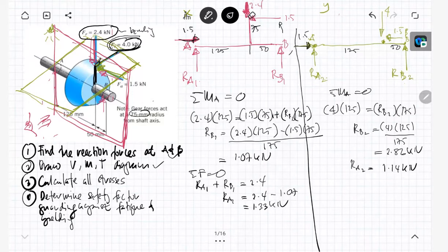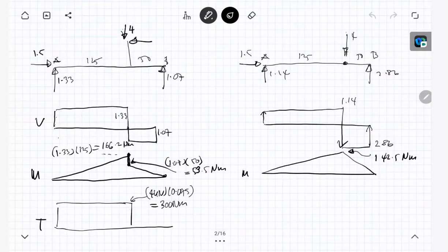This tangential force causes the torque. And this axial force causes the axial load. So we have to consider all those loads, three types of loadings on the gears.